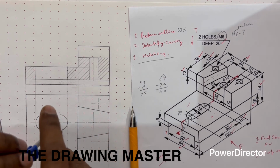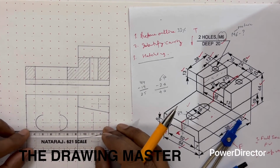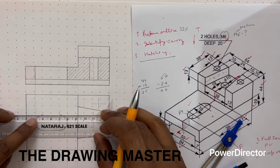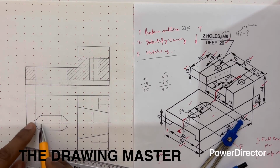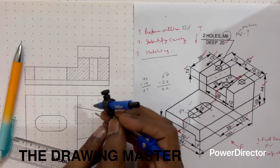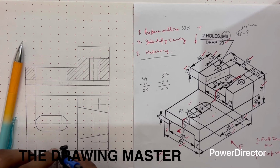We have to simply prepare the drawing as per the given dimension. So now this is 18 and this remaining dimension will become 20. You can check here. This one is 20, the remaining dimension, and the total dimension will become 38. 20 plus 9 this side, 38. So let's draw the dia of 6. Dia 6 means radius 3. So take a radius of 3 mm here.